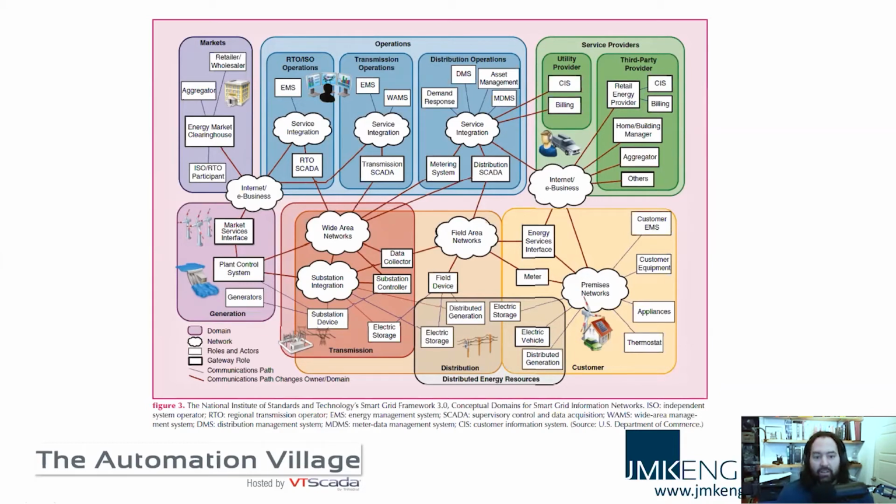An example of some asynchronous status feedback would be the case of a protection relay trip. Within a substation itself, you can have protection that will communicate to a breaker, essentially, with a hardwired connection. That's going to trip that breaker based on a current feedback, voltage, etc. Or you could have a transfer trip scheme from a substation to a generating station, or vice versa. That control action can be outside the normal IT network, stay inside the OT network, and those statuses be communicated back to the system operators, so they can make the necessary changes to their operation. But that can happen relatively slowly, maybe in the time of seconds if it's an automated action, versus the microseconds or milliseconds that the control actions happened.